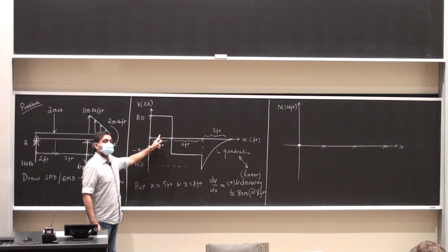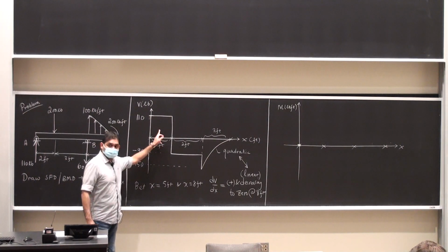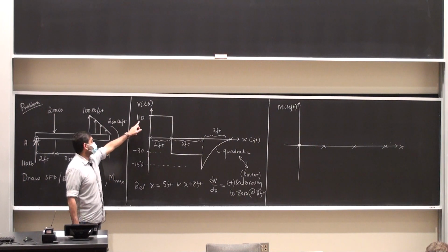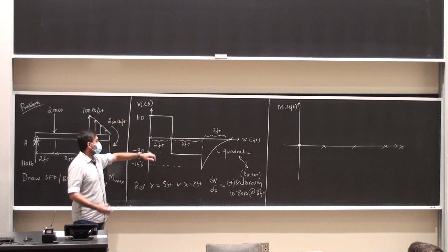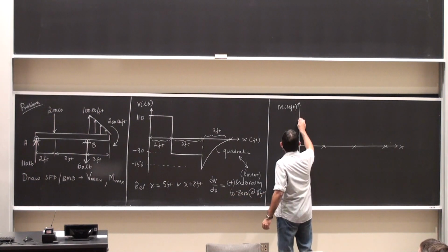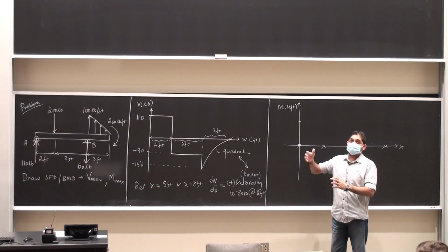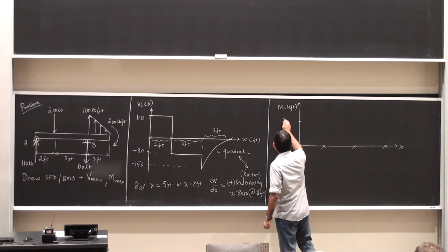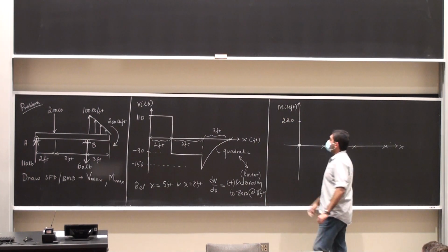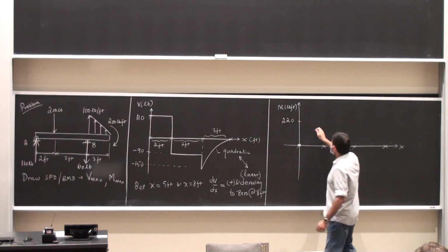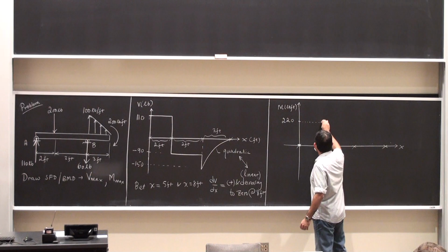The value of the bending moment is going to be the area under the shear force diagram. This is a positive area because it is 110 times 2, so around 220 pound-feet. It's a positive area because I'm looking at the shear force value above the x-axis. So this is 220, which is the area under the shear force diagram. That's going to be the value here.